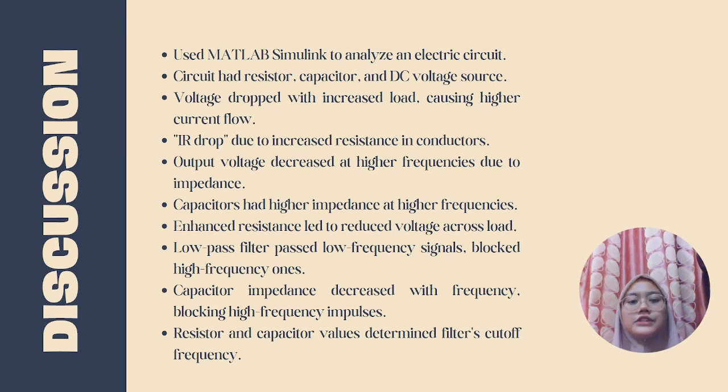A low-pass filter is a fundamental circuit that lets low-frequency signals pass while obstructing high-frequency signals. As the frequency of the signal increases, the capacitor impedance decreases, minimizing or blocking high-frequency signals while allowing low-frequency signals to go through. The filter cut-off frequency is determined by the value of the resistor and capacitor used in the circuit.